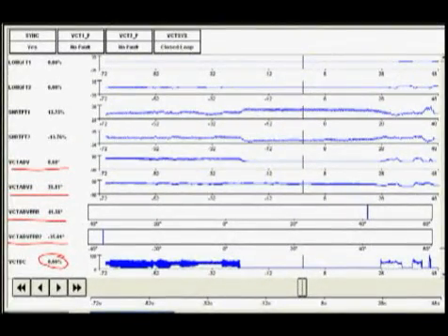The one thing that makes this pretty tricky is that Ford uses cam 2 for its cam crank synchronization. Since cam 2 is the cam that is in error by 35 degrees, the PCM is incorrectly marking where the cams are supposed to be and displaying an error for cam 1 as well. The cam that is not working properly at this moment is cam 2.